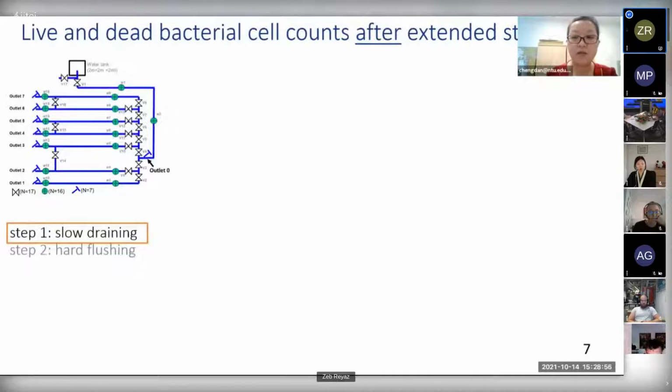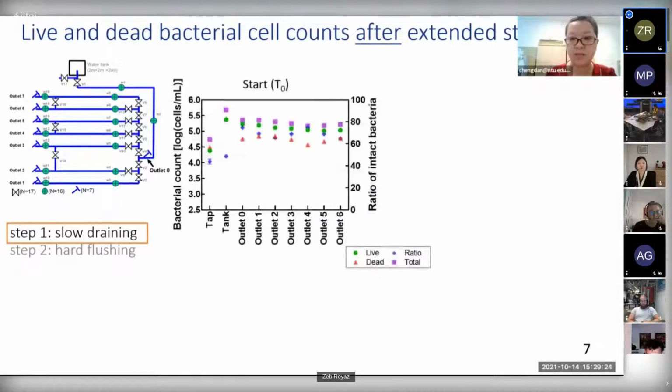In the post-stagnation, 2 tests were conducted. Test 1, stagnant bulk water samples were collected at time 0 and after 60 minutes, respectively, from the small tubing at flow rates of less than 0.1 liter per second in order not to disturb pipe biofilms. Test 2, the pipes were flushed separately at flow rates of approximately 2 liters per second to simulate the hydrological conditions associated with reopening of public buildings. About 250 ml of bulk water samples were collected in sterile Duran bottles at 10 second intervals, up to 60 seconds, followed by sampling every 30 seconds for 5 minutes. More intensive sampling frequency was implemented for the last pipe outlet 6.